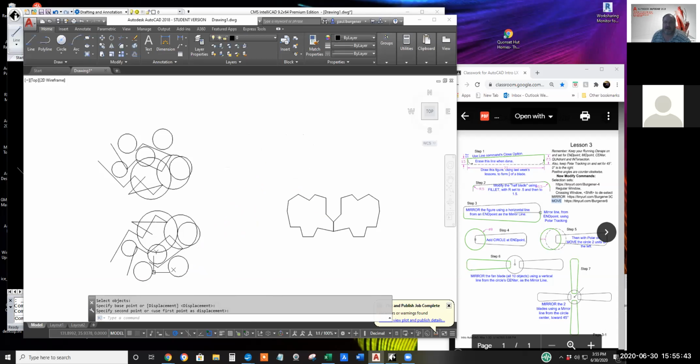Now keep in mind you can move all the ways we learned last week in drawing a line. Remember absolute coordinates, 1,2 to 5,6. You can use absolute coordinates, kind of like latitude and longitude, to make a line, and you can move objects with absolute coordinates. I do that when working 3D, but I don't think it's common in two-dimensional work.